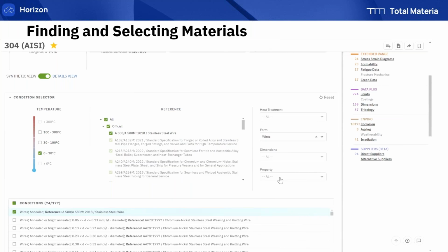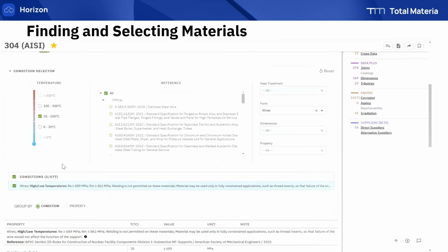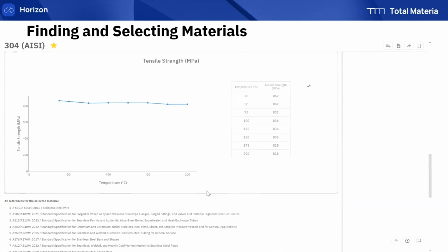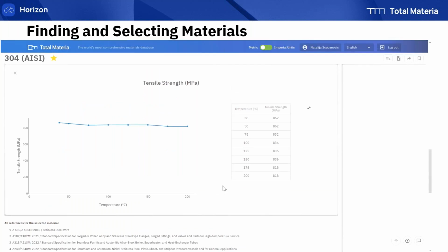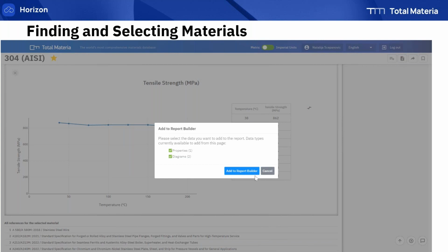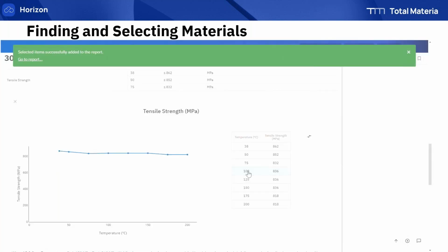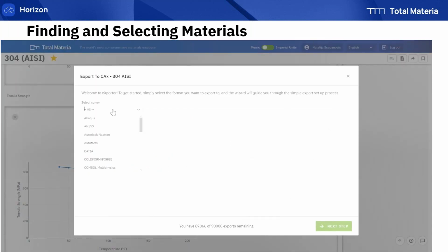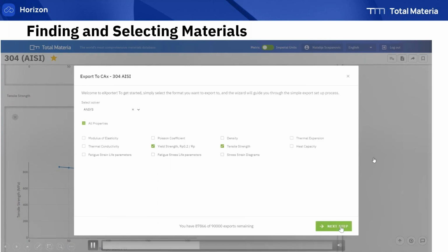You can see the heat treatment forms of the material. Of course, it depends on the form, on heat treatment or dimensions of the material. It affects their properties; mechanical properties are different at the end. Physical properties are different at the end. Can you imagine, different forms of the same chemical composition material can give different mechanical properties? Usually, some engineers make these mistakes when they export this data to their simulation software.